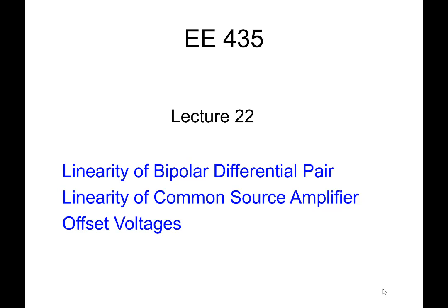You'll have the corresponding counterpart or analogous bipolar op-amp. Compensation techniques apply in the same way as well. About the only exception is we don't have that nice triode region of operation for the compensation to move that right half plane zero back. Oftentimes we'll use a resistor for that in a bipolar process.